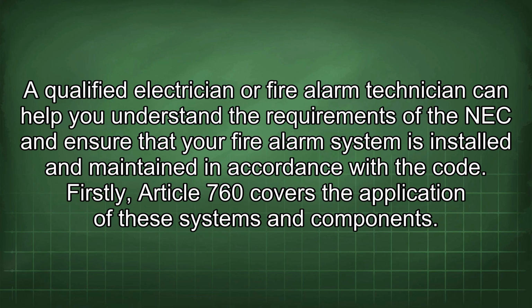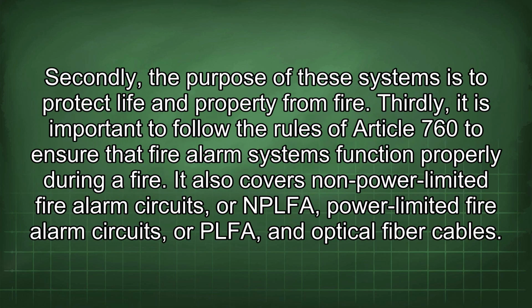Firstly, Article 760 covers the application of these systems and components. Secondly, the purpose of these systems is to protect life and property from fire. Thirdly, it is important to follow the rules of Article 760 to ensure that fire alarm systems function properly during a fire. It also covers non-power limited fire alarm circuits, or NPLFA, power limited fire alarm circuits, or PLFA, and optical fiber cables.